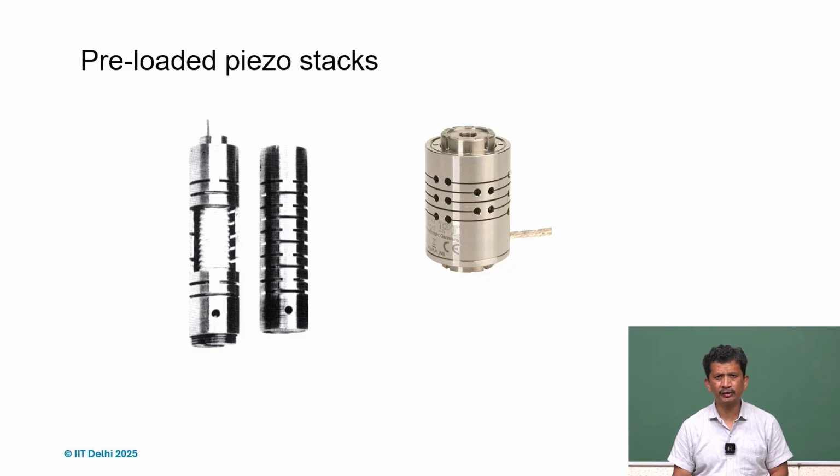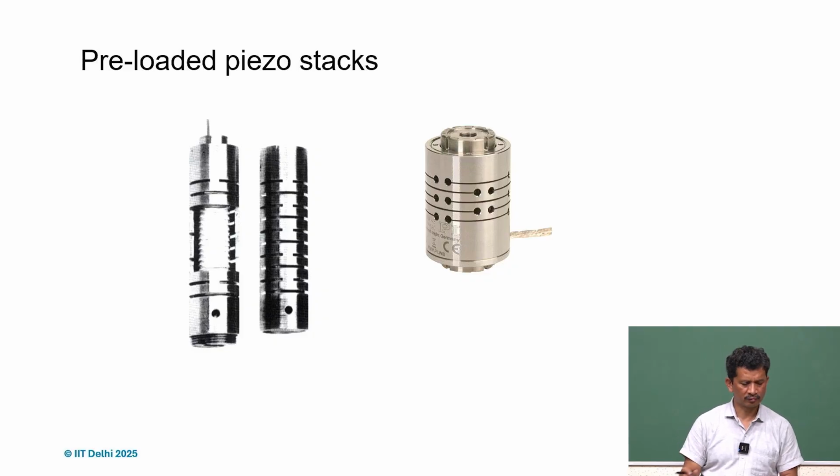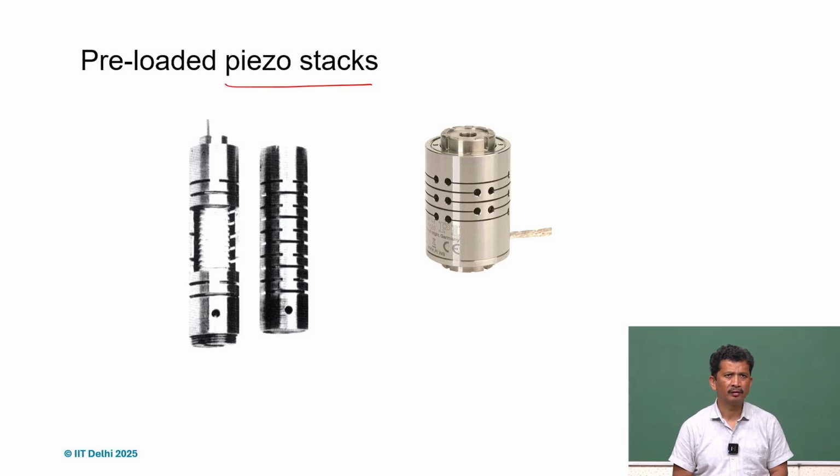So a very good application is for making piezo stacks. If you are aware, for piezo materials it's very important to have preloading to get rid of hysteresis.